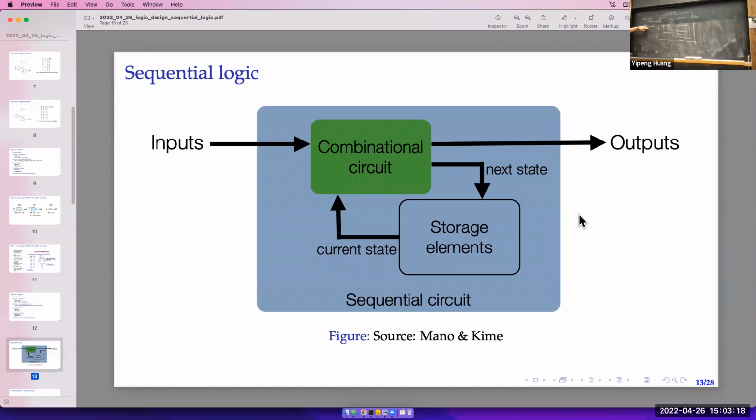Well, there's the data that you want to write to the cache. So this is write data. And maybe you also need another wire that says write or read. You need to tell it whether this address you're giving to the cache is your intention to write to the cache, or are you just trying to read from the cache? So there's a control bit here that says, are you in write mode or read mode? What's the output of the cache?